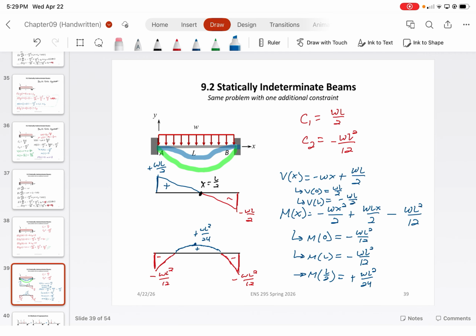Now, one thing to note is if you were designing the structure, and let's say, for example, with the bending moments that you got, what would be the point along the beam that would yield first? Let's say you continually kept applying load more and more until you reached the yield stress. What would be the point of the beam that yields first? Yeah, at the connection points. Now, if it yields, what do you guys think will happen? Remember what happens when a structure yields.